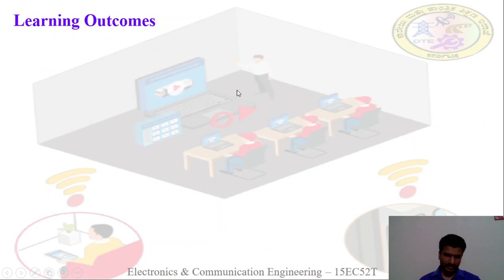So I have taken only two examples for the store instruction. Try these two instructions, STMDA and STMDB, similar to LDMDA and LDMDB. What is meant by STMDA? Store, DA means decrement address by 4 after store. STMDB means decrement address by 4 before store. So that is the difference. You try these two.